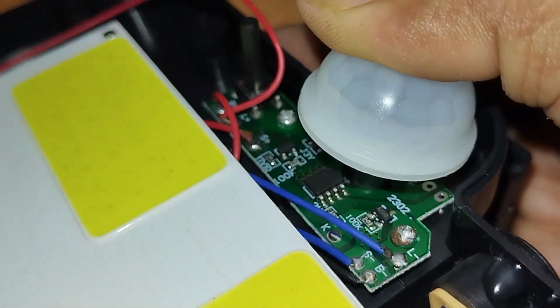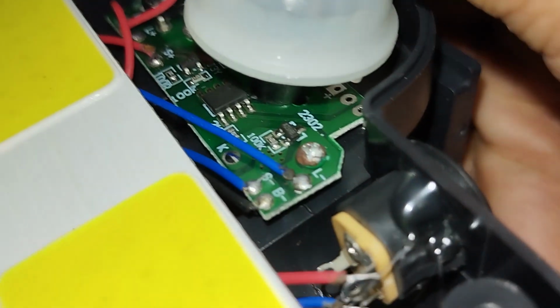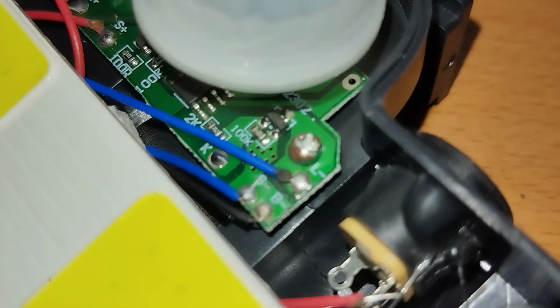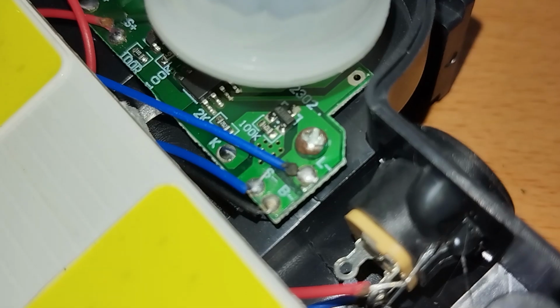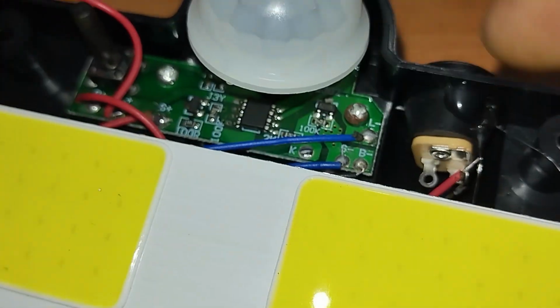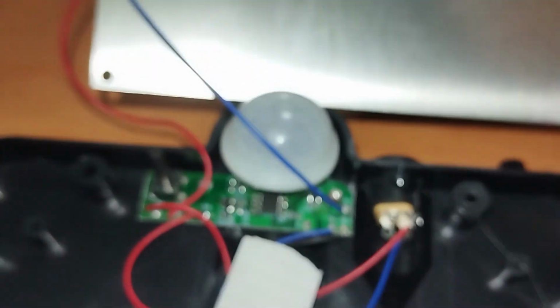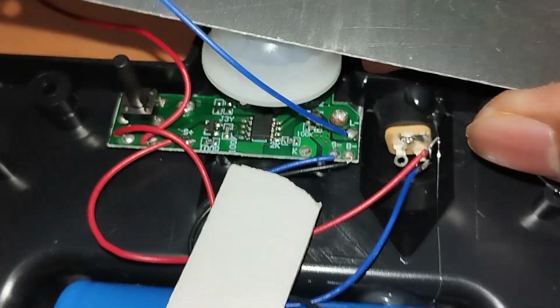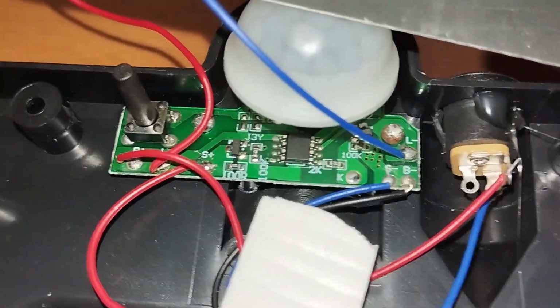On the back I can see a few transistors and IR sensors directly soldered to the board. This board doesn't have any double-sided SMD or electronic components, but it has double-sided connections, double-sided traces. One other good thing is that the traces are almost covered with some protective coating, because that is not conductive. Soldering joints are the only conductive parts of this board. Chip on board LEDs are kind of sticky. Sticky, icky. Away.